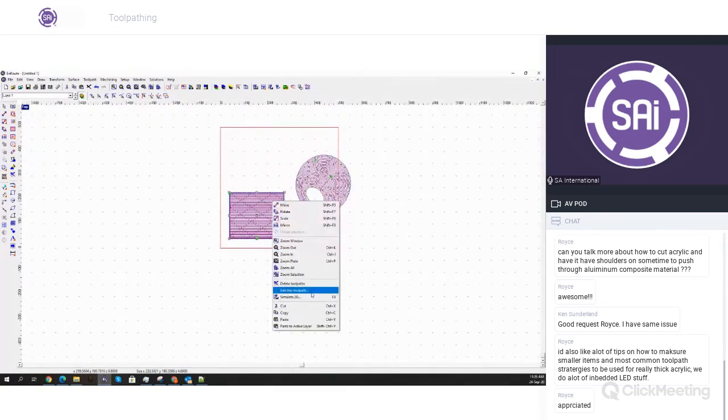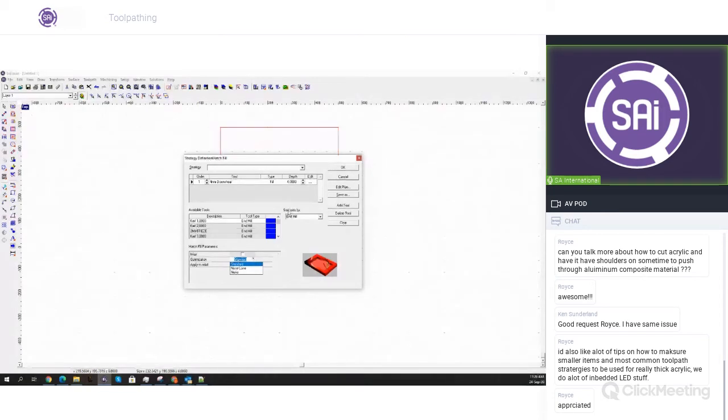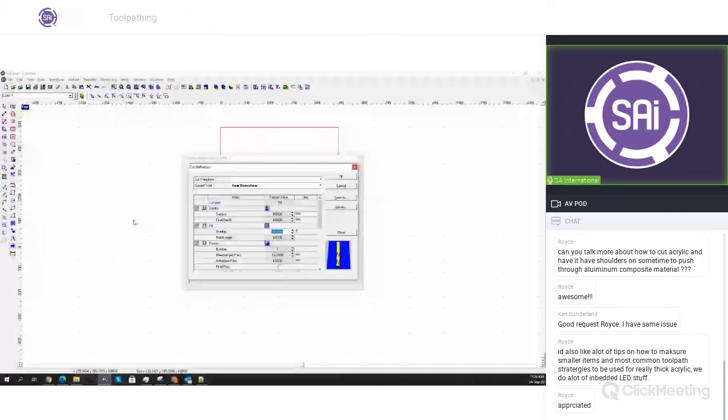As for the parameters, most of them will be pretty close to the ones of the routing offset. In this one, you'll still have the optimizations, which will focus mainly on doing the fewest amount of tool lifts and going back and forth the least amount of times. With the island fill as well as the hatch fill, you'll also always be able to set up an overlap.